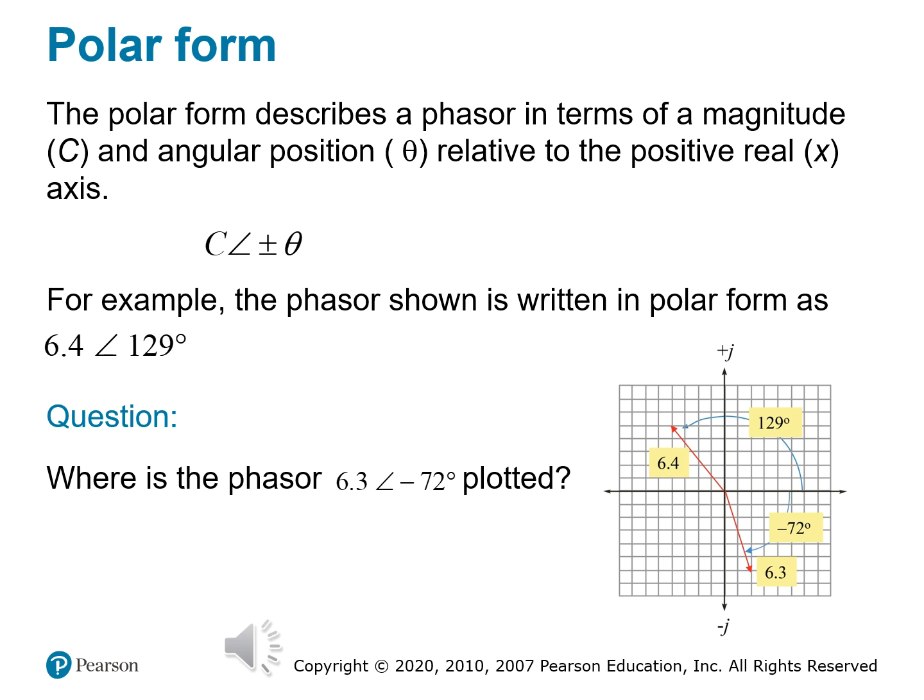And why do we use polar form? Well, polar form is ideal for multiplying or dividing phasors, working with impedance and current-voltage ratios, and visualizing phase differences, especially in RC and RL circuits. It's also the go-to format for interpreting magnitude and phase response in filters. Compare it with inductors. In RL circuits, inductive reactance gives us positive JX, and in RC circuits, capacitive reactance gives us negative JX, and the resulting current leads the voltage. These angles matter, and polar form captures them directly.